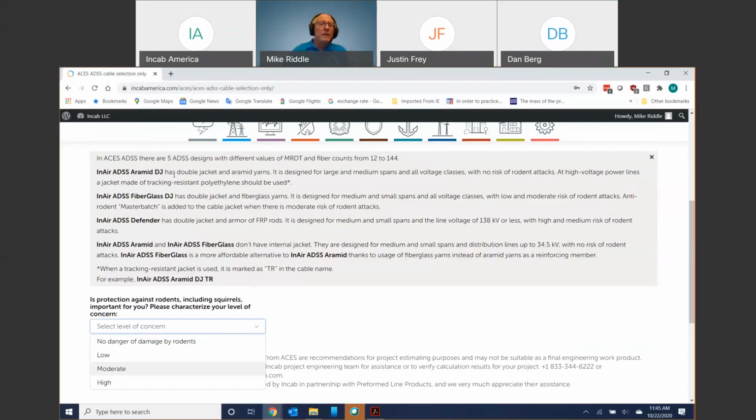Anyway, the way that you get rodent resistant is basically twofold. One is that you can use fiberglass. Just plain fiberglass yarn gives a cable kind of a C level. You know, if you're on school grading system A, B, C, D, F, aramid basically gets an F. Rodents are quite happy to chew on cables with aramid in it.